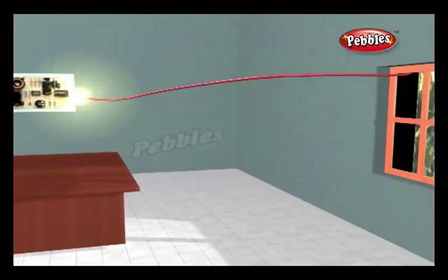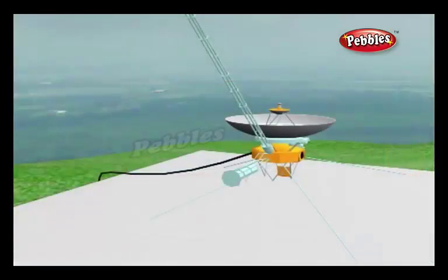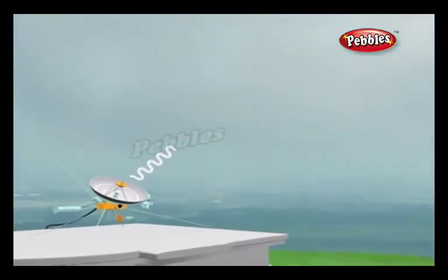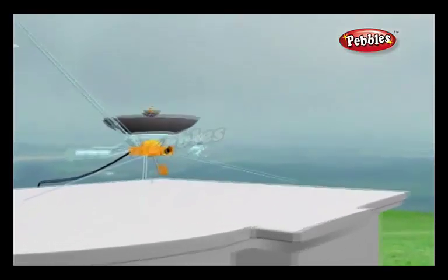Once the radio waves have been generated, an antenna working as a transmitter hurls them into space. The antenna is usually curved so it focuses the waves into a precise, narrow beam, but radar antennas also typically rotate so that they can detect movements over a large area. The radio waves travel outward from the antenna at the speed of light and keep going until they hit something. Then some of them bounce back towards the antenna in a beam of reflected radio waves, also traveling at the speed of light.